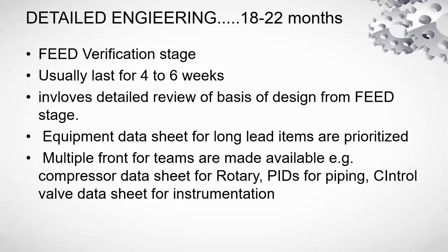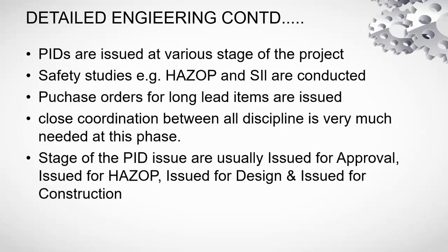For example, compressor data sheets for rotary, static equipment data sheets for mechanical, P&IDs, where the initial issue of the P&ID is shared with all disciplines, control data sheets for the instrumentation team, and likewise other discipline interaction, which includes mechanical to electrical and piping to civil for structurals and pipe racks. Yes, those are also started in this phase.